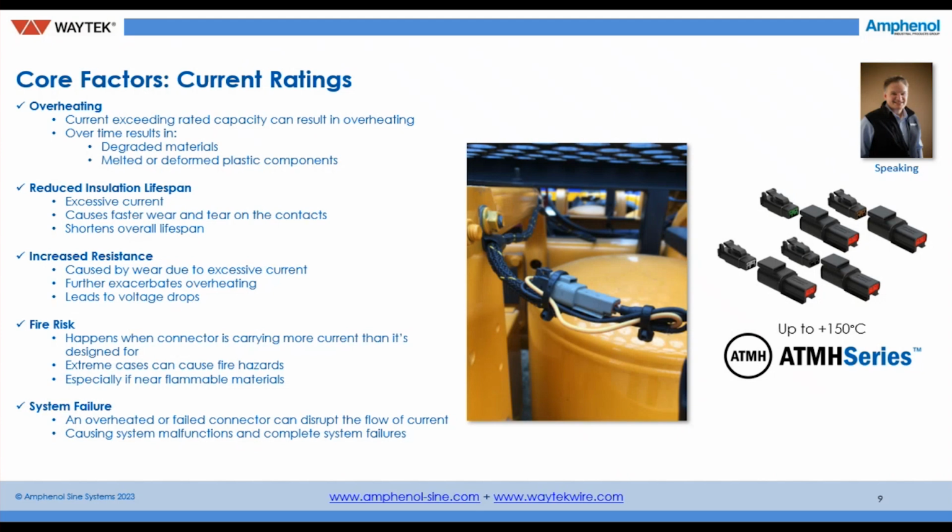Increased resistance. This could be caused by wear due to excessive current, further exacerbates overheating, leads to voltage drops. Fire risk. Certainly, we've seen this, very unwanted. Nobody wants this. V0 comes into play, flame ratings, vertical, horizontal. But this happens when the connector is carrying more current than it's designed for. Extreme cases can indeed cause fire hazards, especially if near flammable materials such as transportation or the automotive applications that we often see these connectors fall in.